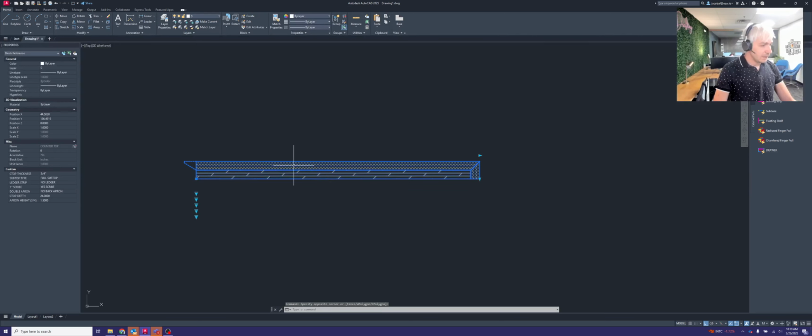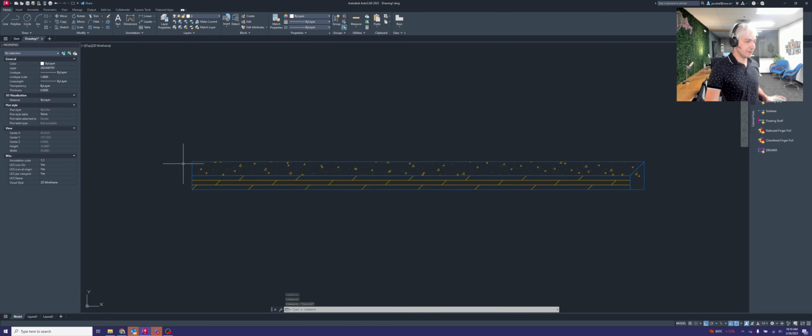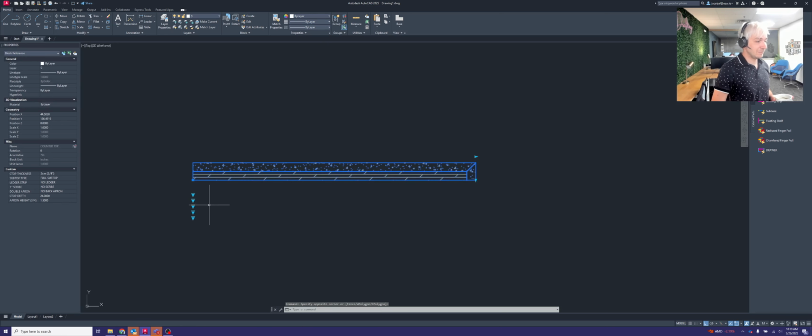If you have a countertop that is made out of solid surface or stone, you will not actually have the ability to scribe that. So what we'll do is the installers will take a caulk gun and they will caulk that countertop to the drywall to fill in that gap. So stone and solid surface, we do not scribe those to the wall, just to make note of. The block prevents you from doing that too. So in case you forget, it's made so you can't do that anyway.